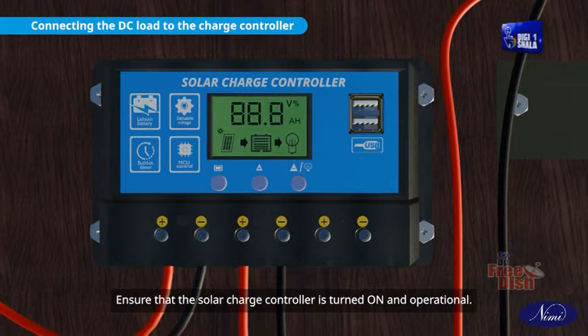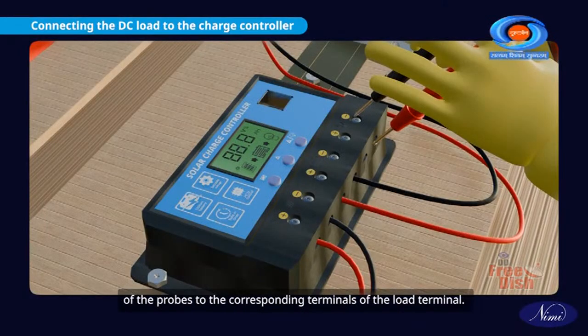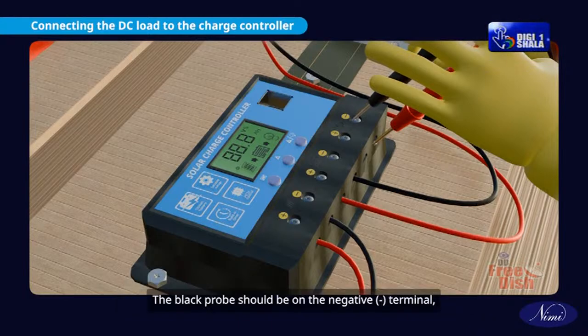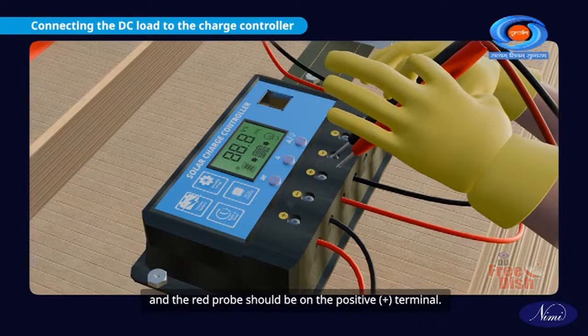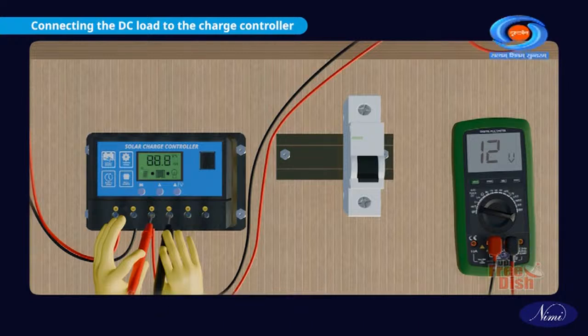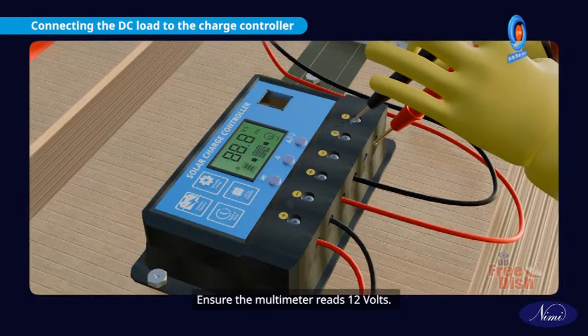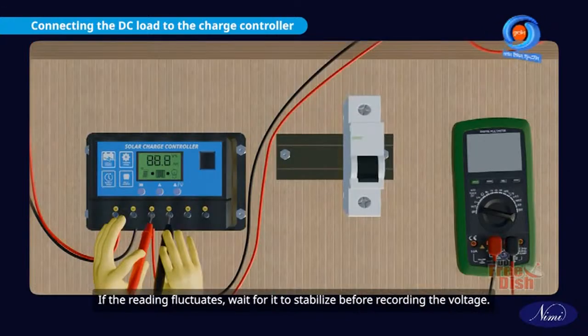Ensure that the solar charge controller is turned on and operational. Touch the metal tips of the probes to the corresponding terminals of the load terminal. The black probe should be on the negative terminal and the red probe should be on the positive terminal. Once the probes are securely in place, read the measurement displayed on the multimeter. Ensure the multimeter reads 12 volts. If the reading fluctuates, wait for it to stabilize before recording the voltage.